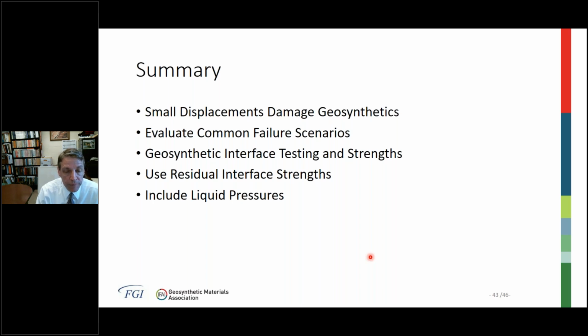Second bullet point in the summary. Remember the 7 analysis/failure scenarios that should be considered. That should be a checklist. Make sure your facility, when it encounters those typical scenarios, such as liner construction, cover construction, interim slopes, check the filling diagrams between cells and evaluate the slopes between adjacent cells to make sure that an unstable condition doesn't develop. Because if the final build out of the facility is stable at, say, a 4-to-1 slope or a 3-to-1 slope, it doesn't help if the facility fails before it gets to final build out because a 2-to-1 or a 1.5-to-1 slope develops.